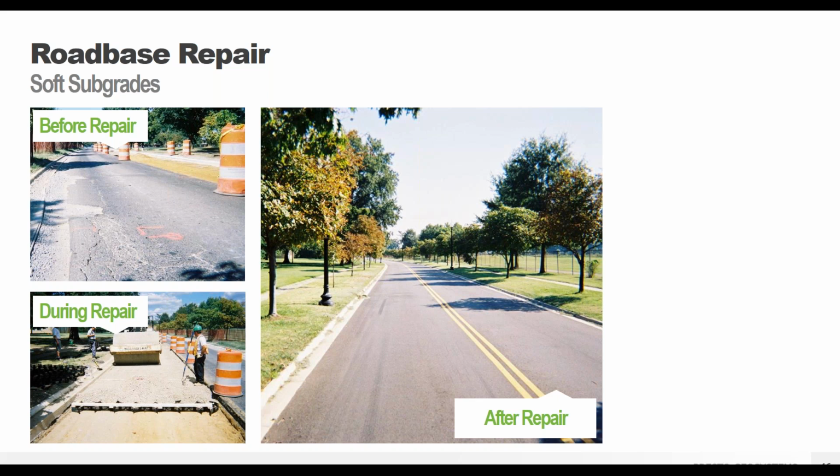So this is a pretty common project that we see. I'm sure we've all dealt with roads like the one in the upper left. Surface cracking, ruts, lots of patched areas that seem to start failing almost immediately. So this is what happens when a road is built over that weak base layer that can't fully support vehicle traffic.